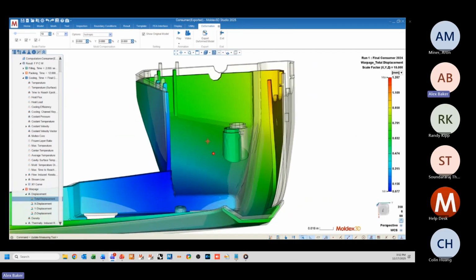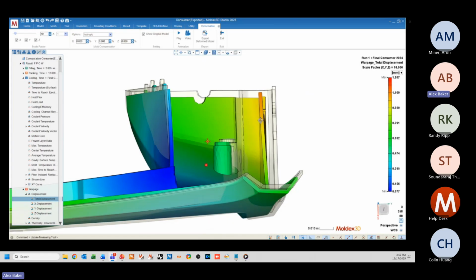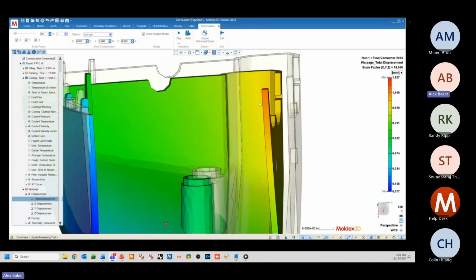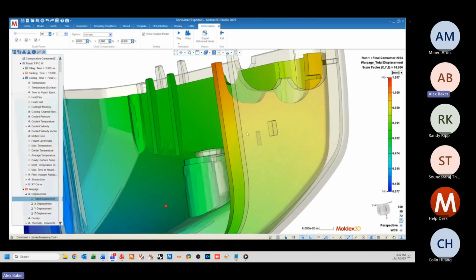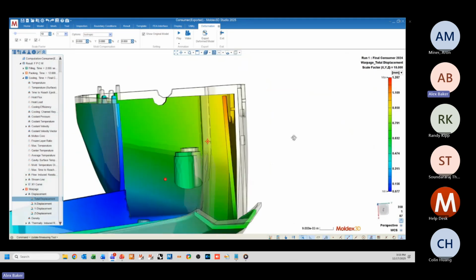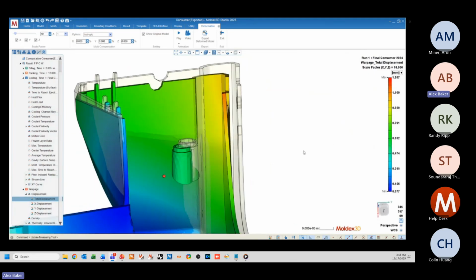And so we see that wall kind of collapsing inwards. Again, this is 10 times scaled, but this is a good indication of, if I have a tolerance that I need to hit, for example, if this window needs to fit into something, then I can get an idea of what areas of my part are going to be contributing to the part being out of spec.